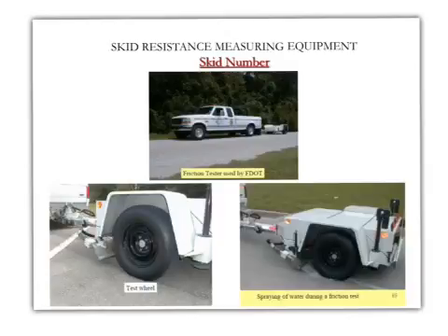Here is more of a schematic to show you how we measure the skid resistance. For example, the very first picture here is the friction tester used by Florida DOT. You could see the vehicle in front, and then we have the tire here to measure the skid resistance. This is the test wheel, tubeless, and it has certain specs mentioned in the ASTM standards.